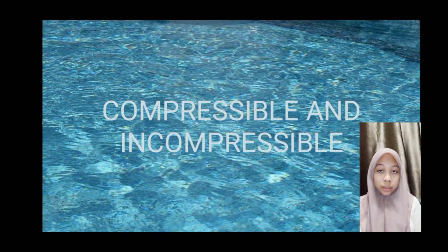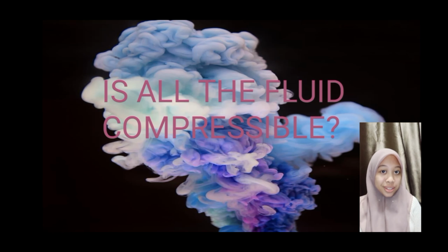A fluid is compressible, so that its density will change with pressure, but under steady flow conditions, provided that changes in pressure are small, we usually say the fluid is incompressible and has constant density. However, in unsteady flow conditions, high pressure differences can develop and the compressibility of the liquid must be taken into account.